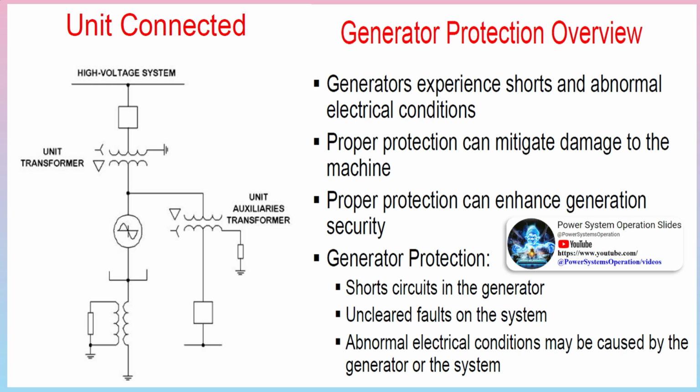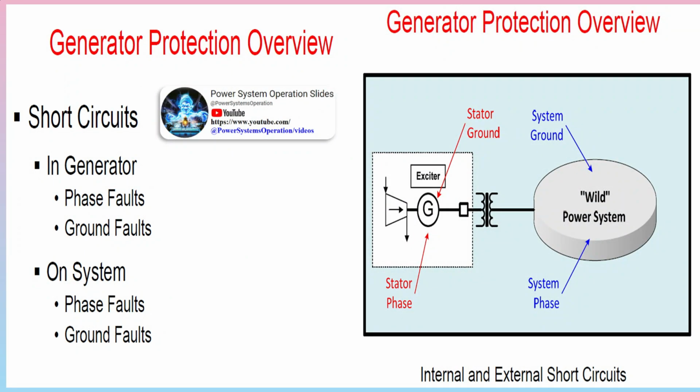But in the latter case, the earth fault loop is restricted to the stator winding and primary winding of the transformer, hence there is no need of grading or discrimination with other earth fault relays in the system. That is why an instantaneous relay is preferable in this case.